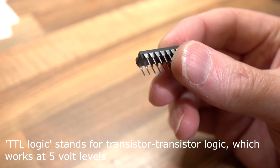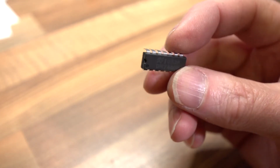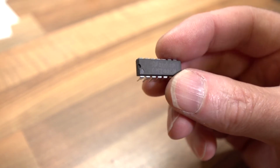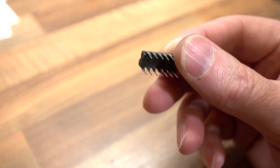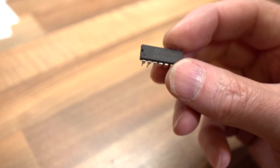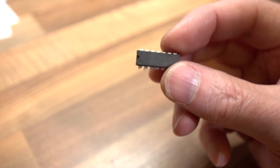You get lots of different types of gates, logic functions, and typically in these kinds of packages, although these days a lot of them are surface mount, so they're even smaller. But these are quite common, and you see a lot of them in beginner circuits. When you're starting out, you tend to use these, but you still see them in some commercially produced products as well. Less so now, nearly always surface mount now, but the functionality is quite similar. And as I say, that's got 4 2-input NAND gates, quad gates in the one package. That's a 7400, so let's put it into the protoboard and power it up and see what it does.